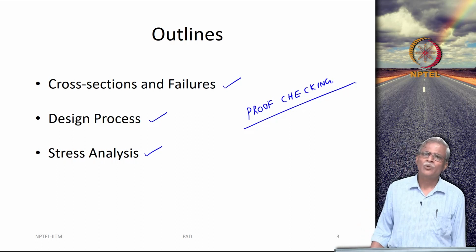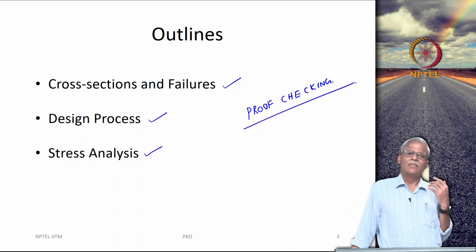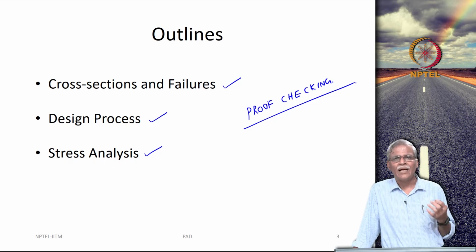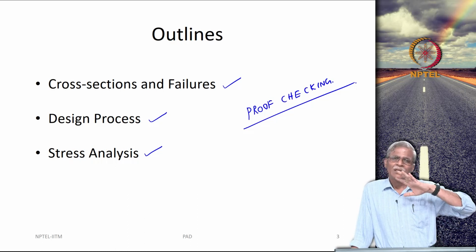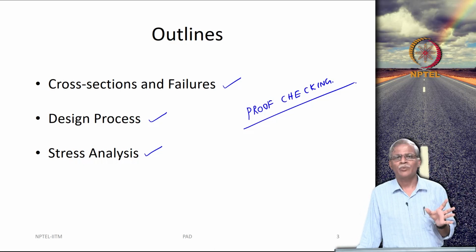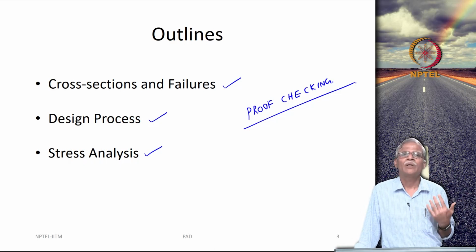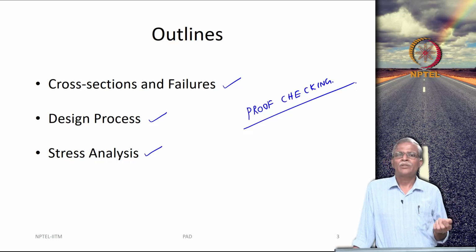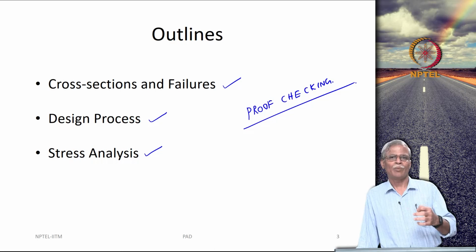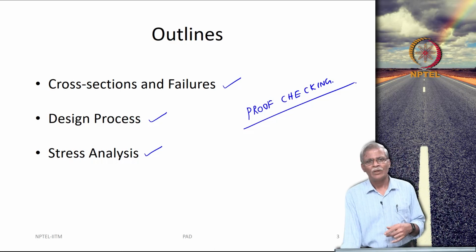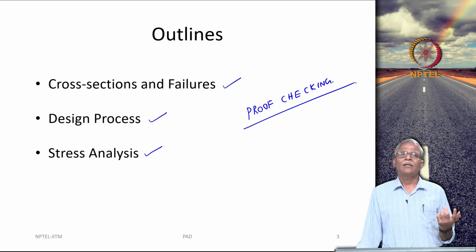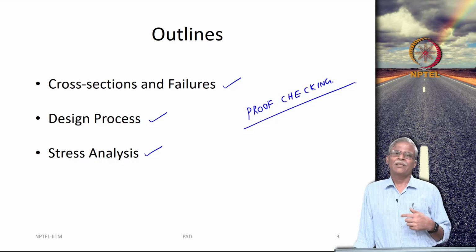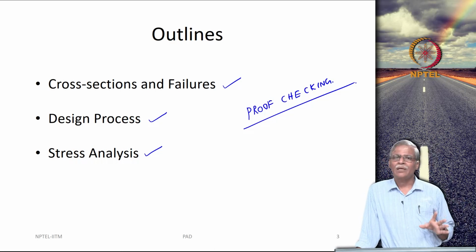That means most of the time, based on past experience, we have a very clear cut idea of what kind of layer thickness should be provided. Most of the time this comes more from the constructability aspect. Obviously, when you are constructing a pavement, you are not going to tell your highway engineer to construct a 45.22 mm layer thickness; that is not going to be possible. The nominal maximum aggregate size, the ability of the roller to compact, the relation between the maximum aggregate size and the layer thickness, all of these things play a critical role.